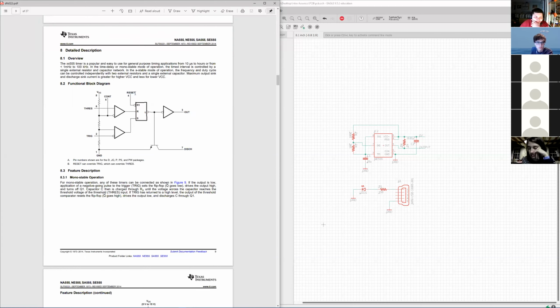All right, so here we go. Reset is the reference. I'm going to call it a comparator because this is what I used. This is essentially a comparator at this point. So we have our reset and our R and our S. When R and S go above half of VCC, which is our reset, then the flip-flop goes high and outputs the buffer thing. Oh, wait, no. Yes, that makes sense. All right. So we open the gate. That opens the gate of the transistor, which discharges it through the transistor and through the output buffer. All right, there we go.